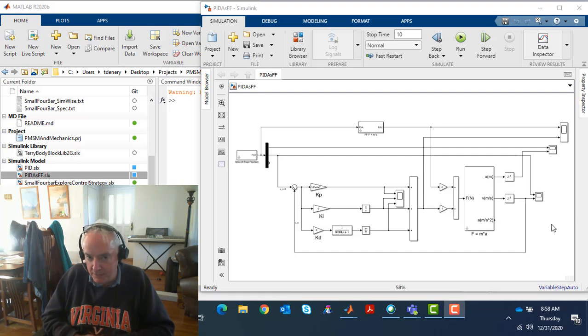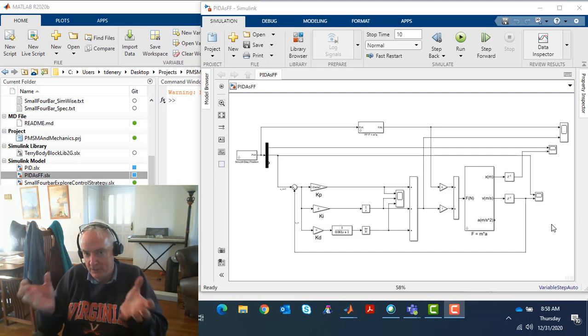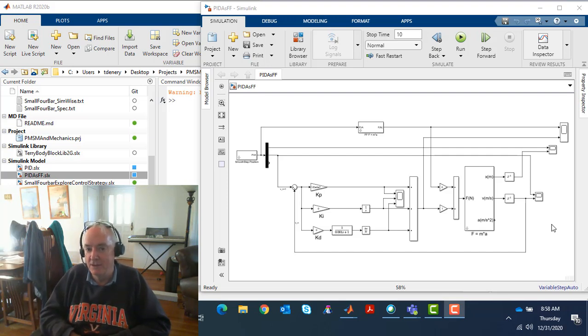The paved path is using PIDs, right? So in a way, you could say I'm saying let's disrupt that a little bit. But at the same time, let's tip our hat and say that path got paved because it really did work pretty well, and part of that was that it can act like a feed forward approach. But the problem with believing too strongly in that is that it can act as a feed forward approach for a small subset of systems, mostly systems that are linear in nature, like F equals ma. You just integrate it twice and you get position, that is, the simplicity of a single mass. And real machines are nowhere near that simple.